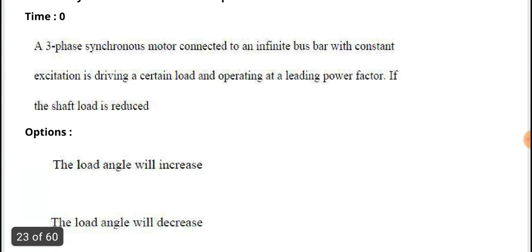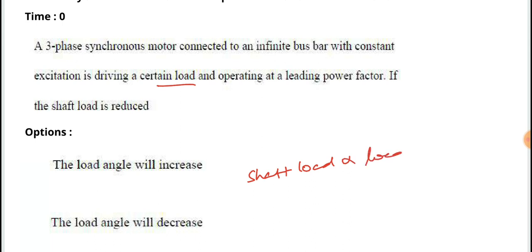Next one, a three-phase synchronous motor connected to an infinite bus bar with a constant excitation is driving a certain load, operating at a leading power factor. If the shaft load is reduced, what will happen automatically? So shaft load is proportional to load angle, so the load angle will decrease. If the load is reduced, it means the load angle also decreases here.